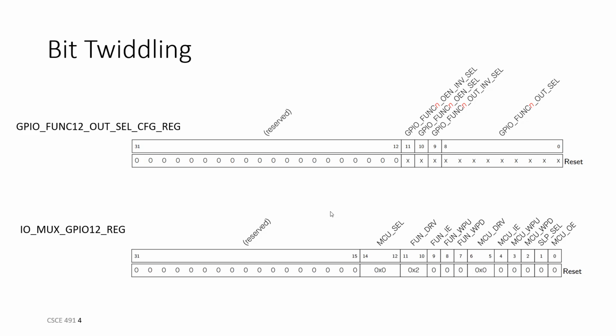Now in my code, I would do a read followed by a write followed by a read, because I wrote my code so it reads back even after I write to confirm that my write worked. Because if you get the address wrong, you can make your code more robust and be able to detect errors by reading the value back and confirming that the write worked. Because one of the things that happens with these control registers is that if you write to the wrong register, chances are it won't even allow you to write to it. But there's no kind of acknowledgement from the hardware. The only acknowledgement you can get back that your write worked is if you read the value back and confirm that whatever you tried to write actually worked, right?